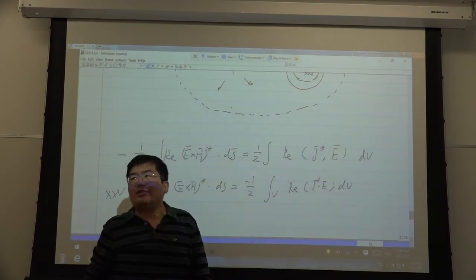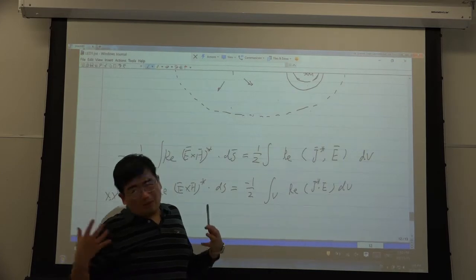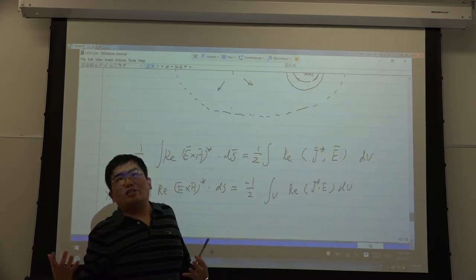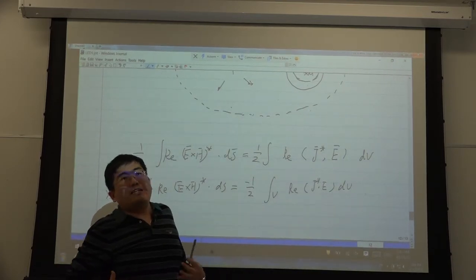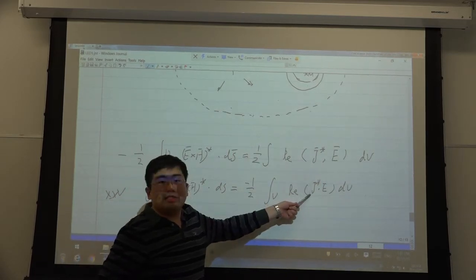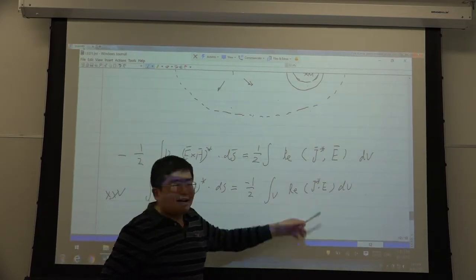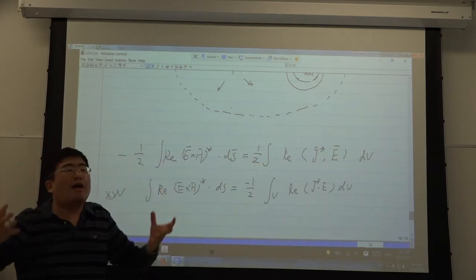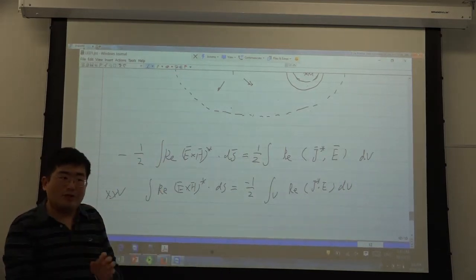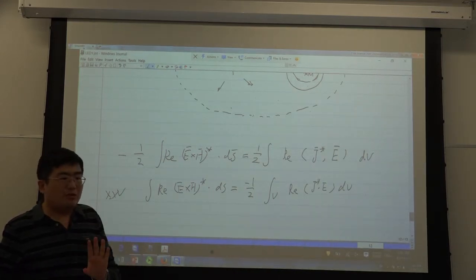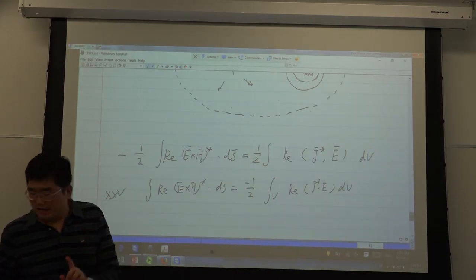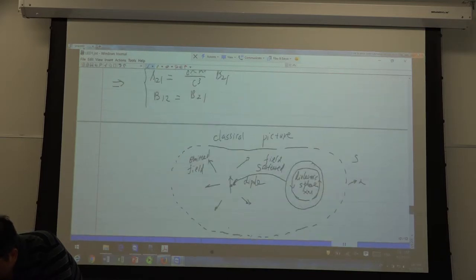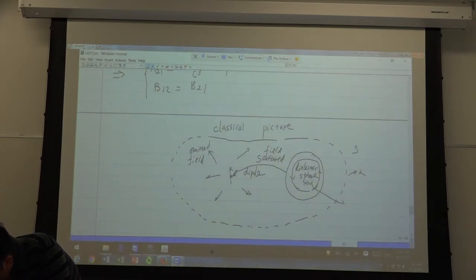You derived this equation before, but your derivation did not contain a source. You just assumed some lossy material, J equals sigma E, right? So there is a sigma E squared term similar to that. It means there is power absorbed by this absorbing material. Here, there is no absorbing material because the dielectric is lossless.